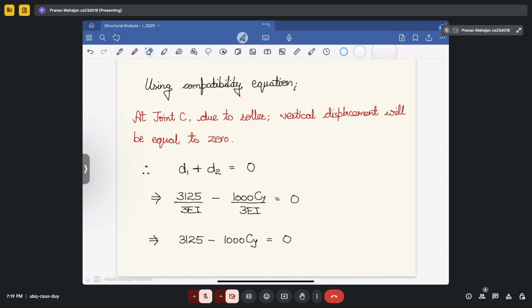That matrix method is based upon this force method only, but you map up all the values that you observe at different points of the structure, and then you find one matrix that you call a flexibility matrix, and then you solve for the unknowns in the structure. It will help you in understanding the whole structure, not only for basic beams, but when the structures are very complex, and how you will be able to determine the value of unknown forces in the structures.